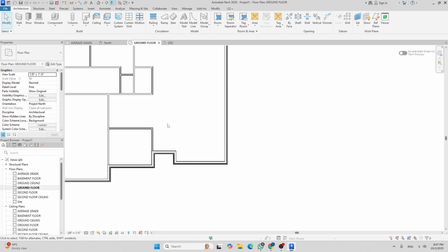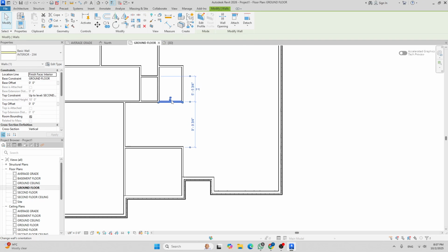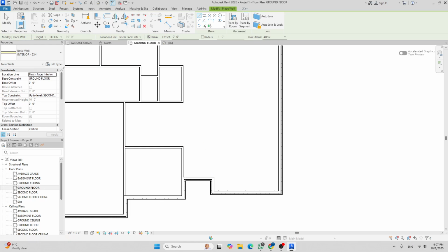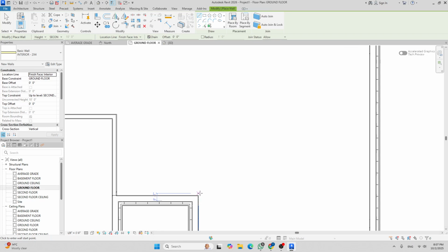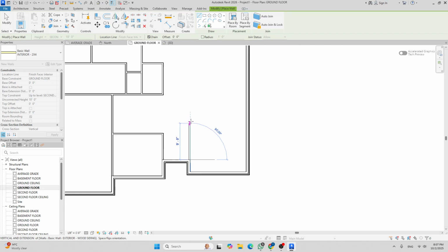So when drawing walls, you can click the command wall to draw it, or you can click a wall and use this create similar tool, so it will get you to that command without having to set any constraint whatsoever. I'm gonna draw a wall from here, move up about here, and then move it to the right. I'm gonna hit escape 1 time.